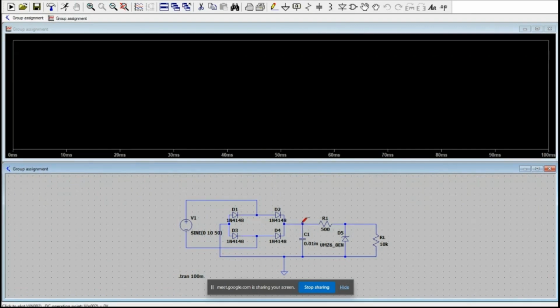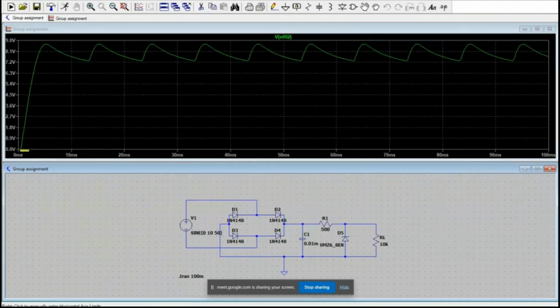Okay, the next one I will be showing the voltage through the filter. As we can see, when the capacitor charges until the peak, it discharges very slowly, and then when in contact with the pulsating DC again, it charges and discharges. This reduces the ripple from the 2 peak of the wave.